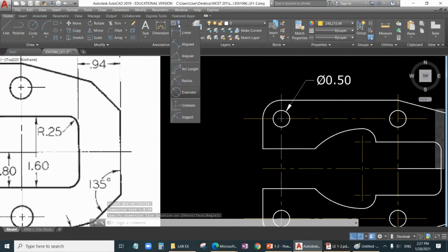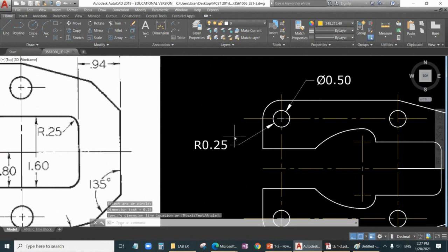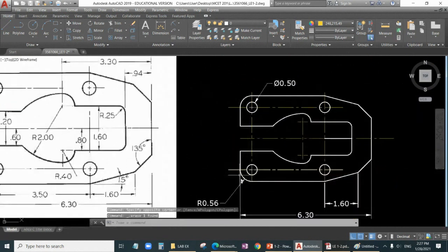The program will give you, okay, maybe in some exceptional cases you want, it will give you, but this is not a good way of showing the dimension. With full circle, diameter. Partial circle, radius. It must be shown always like that. You can show the other dimensions.